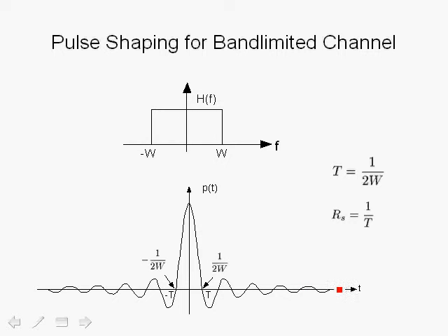Of course, this is a well-known property of the Fourier transform and inverse Fourier transform. So one problem of band limiting a signal to a fixed bandwidth is that in the time domain we'll have a very long time extent, as is shown in the case of the sinc function here. If we have a filter which has an impulse response which is the sinc function, then we know that in the frequency domain it would be band limited and will meet our requirements for transmission over a band limited channel.